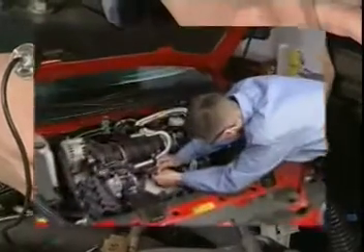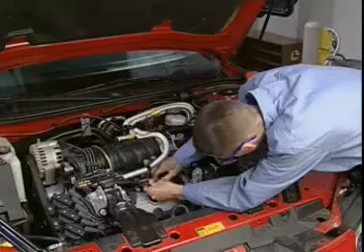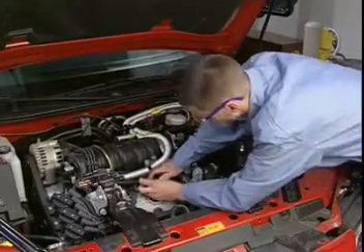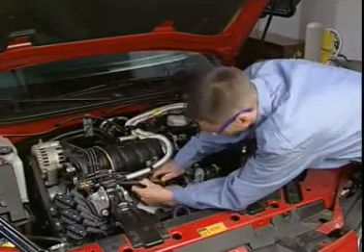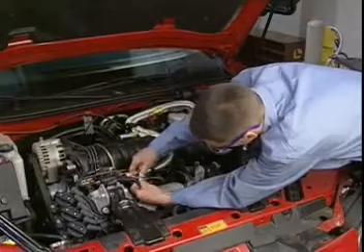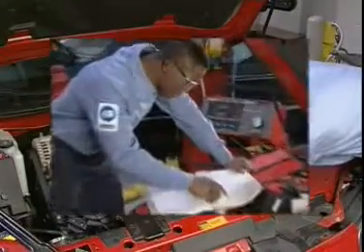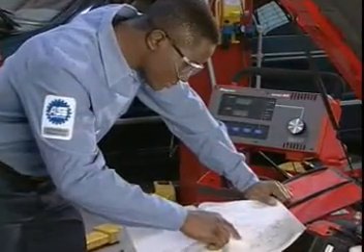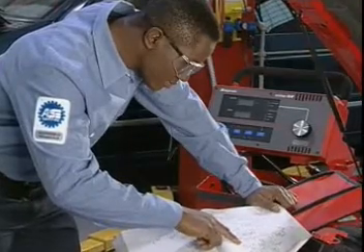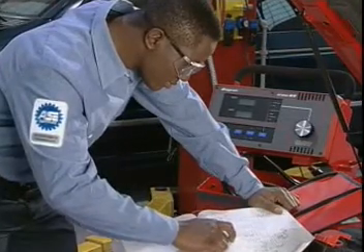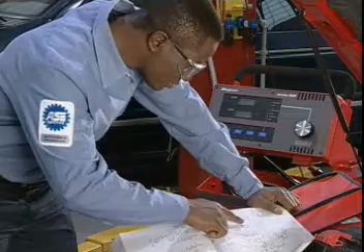Check the circuit for good electrical connections. The connections must be clean and tight to prevent additional resistance. Let's see the proper way to do this. A technician should always consult a wiring diagram called a schematic to determine appropriate test points before checking circuits.